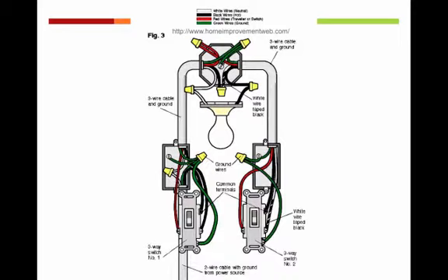But what happened is one of the switches was actually a master for the power. So when it was off, nothing worked. I could flip the other switch all day long and it didn't turn the light on, which means that the travelers were not connected correctly. It really works best if all of your wiring is color-coded or labeled well. That is not always the case. Sometimes you'll get into an old circuit box and you'll realize all the wires are exactly the same, and this is where it helps to have some kind of test light or some kind of meter that you can check for connectivity. So anyway, I'm going to go ahead and explain this diagram a little bit.